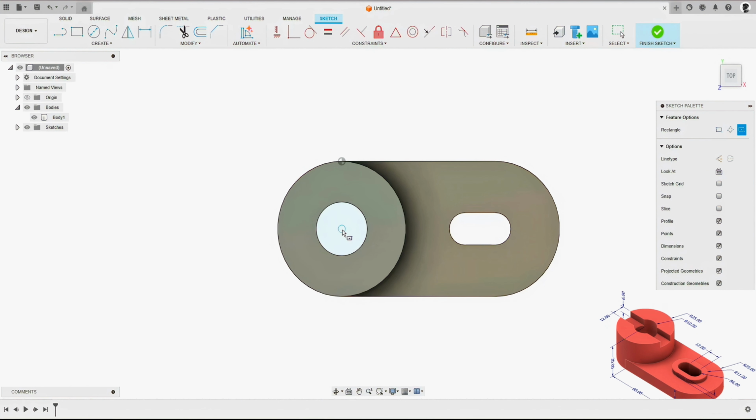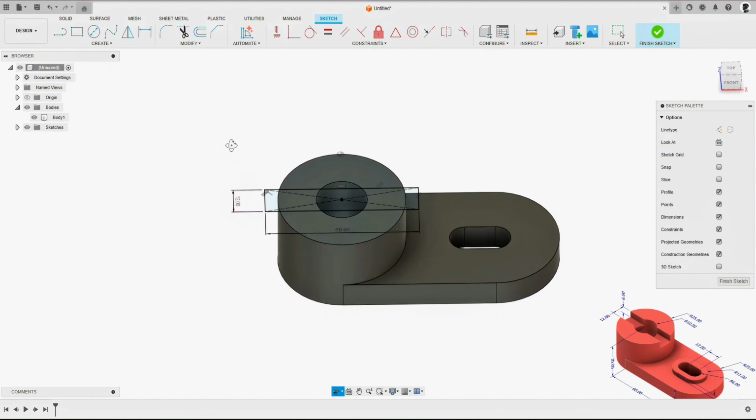Let's left click once, snap on there, bring out our center point rectangle. Want to make sure this comes exterior of the 50 mil circle. And we're entering a length there of, let's say, 60 millimeters. Press tab on the keyboard. And then the width of this slot is 12 mil. Press enter. Our geometry in place there.